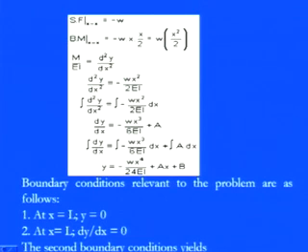So again you see the same procedure which we followed for the point load here. For the UDL also, the slope dy by dx is nothing but equal to minus Wx cube by 6EI, because the square term is there. So x cube by 3 will come, and since 2 is already there in the denominator, we have minus Wx cube by 6EI plus a. So now this is the one equation for the slope condition, dy by dx equals minus Wx cube by 6EI plus a.